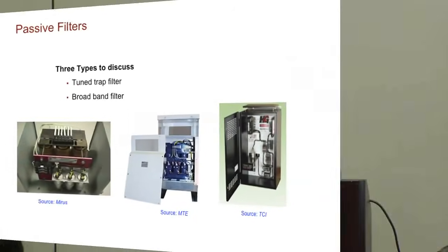Performance can be reduced by a line imbalance, a voltage imbalance. One leg is lower than others, right? No, not out in our world. Everything's perfect, right? All nicely even, perfectly balanced. Some things that you've got to be aware of is your power factor might go leading as well with these filters, so you've got to be worried about that. Watch that. Be careful of that.